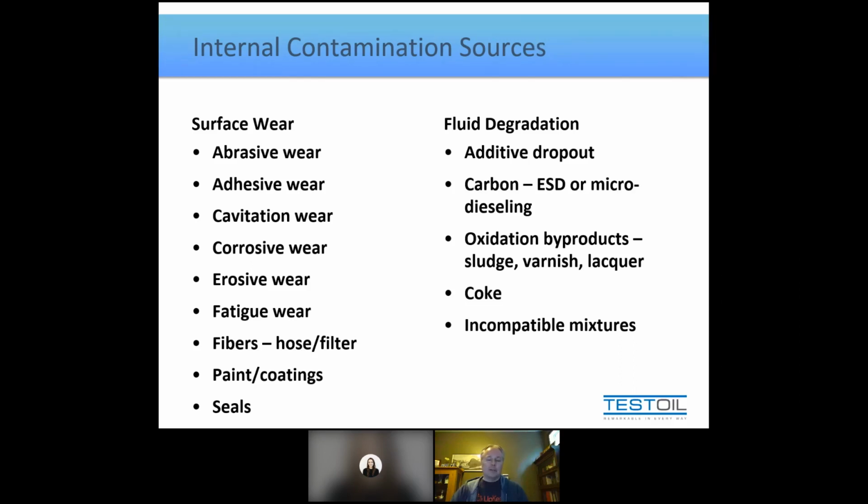So there's the obvious gels and precipitates that form when you have incompatibilities or additive dropout from mixing of different fluids or contaminant in the fluid. But then there's unique ones like carbon. Carbon is created through thermal events. And two of the most common types of thermal events that create carbon particles within the oil are microdieseling or electrostatic spark discharge, otherwise known as ESD.